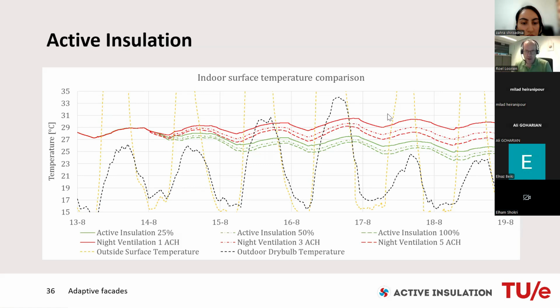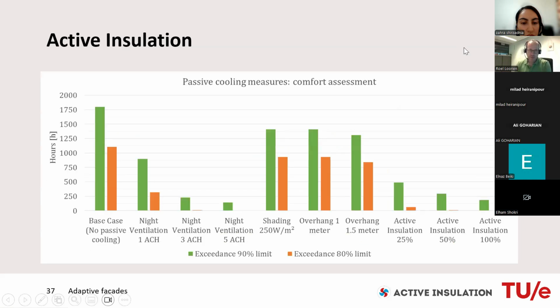And when we look at thermal comfort in this case, so this is for the summer situation. It's a residential building in the Netherlands where usually we don't have air conditioning. But in this case, on the bars on the left, we can see that around 1,500 hours per year, we would actually have overheating in a well-insulated dwelling.